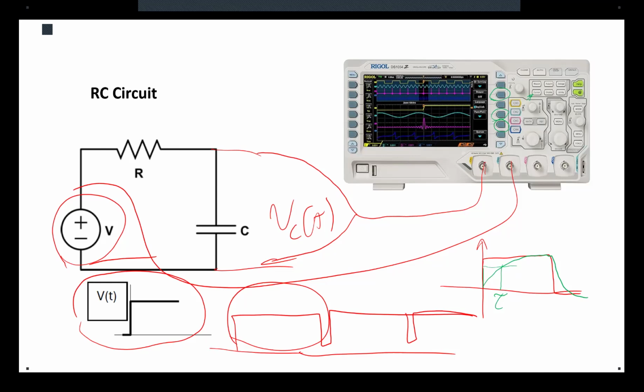So, for example, you choose the horizontal one, and you click on A. Now this pin would change the position of the A cursor, the horizontal A cursor. And if you push the button for B, now you have control to change the position of the horizontal B cursor. You push to change the horizontal to vertical, and it's the same. It has A and B.